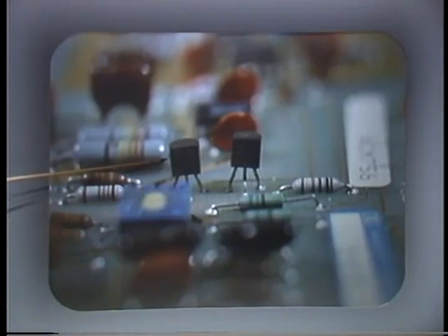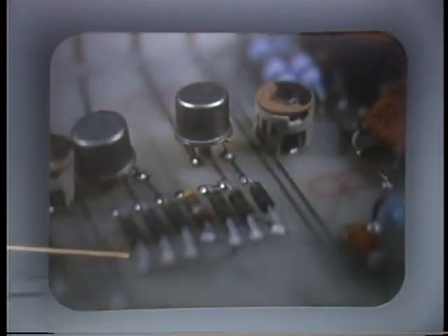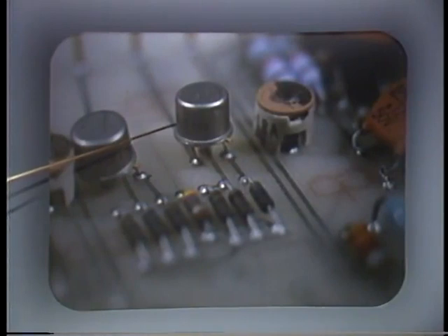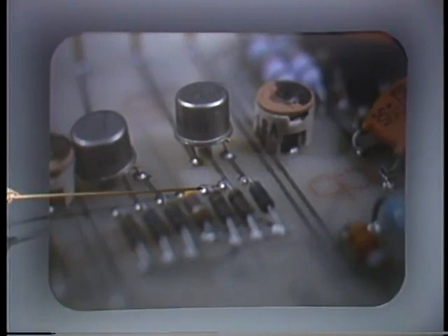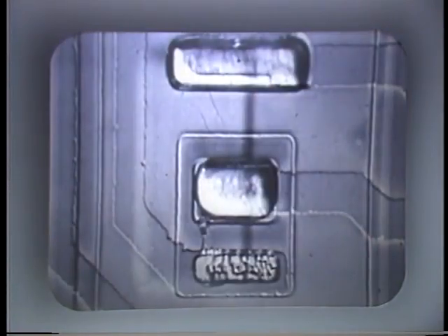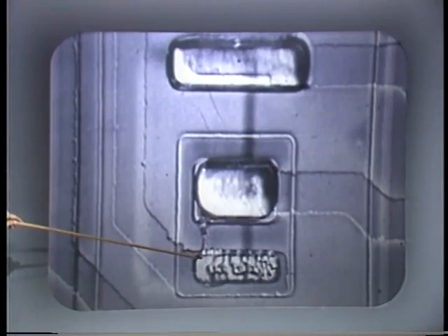Here is an example of a small signal transistor, in this case in an epoxy package. Here is a transistor in a metal can, and here are some axial-leaded components. One of them might be a silicon diode. All of these bipolar components can be damaged by static zap. When they are, we can look inside with a microscope, and this is what we see. The narrow fracture between the base and emitter pads of the transistor. There is now a short circuit between those two, and the transistor is no good.